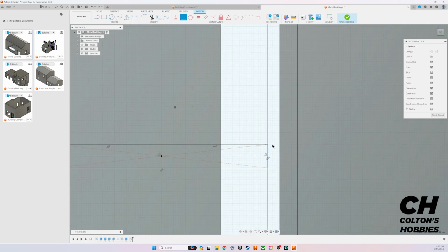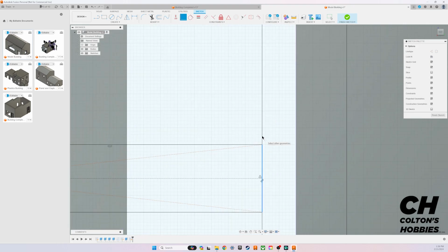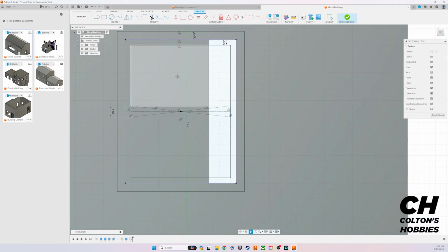Yeah. And then I'm going to select this line that goes vertical, or actually I can just do a point. So I coincident the line to this center line, construction line point, and now it's going to stick to that line. This edge, the side of the rectangle will not go right or left. It'll stick to that point because of the coincident constraint. So constraints can be helpful.